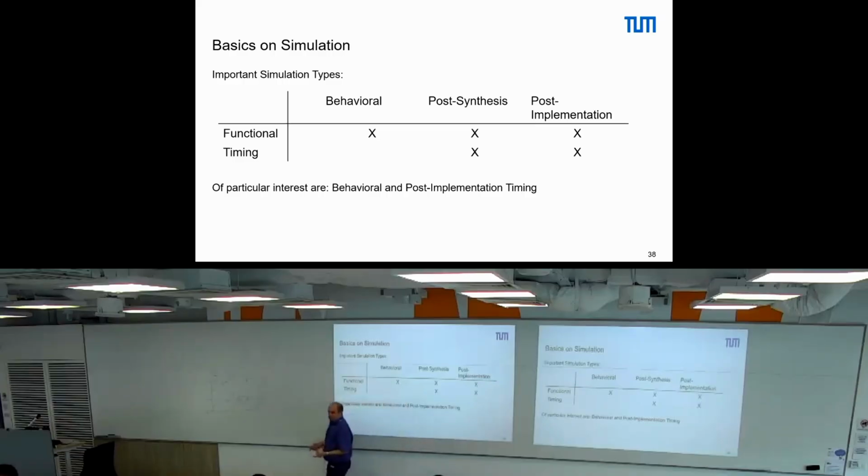For the behavioral simulation, so to come back to my original question, why here is a gap. For the behavioral simulation, we start effectively with what I gave you at the beginning, right? I gave you no information what the delay of the gates is. I gave you no information what the delay of the wires is, so you cannot estimate what the frequency is, the maximum frequency. Okay?